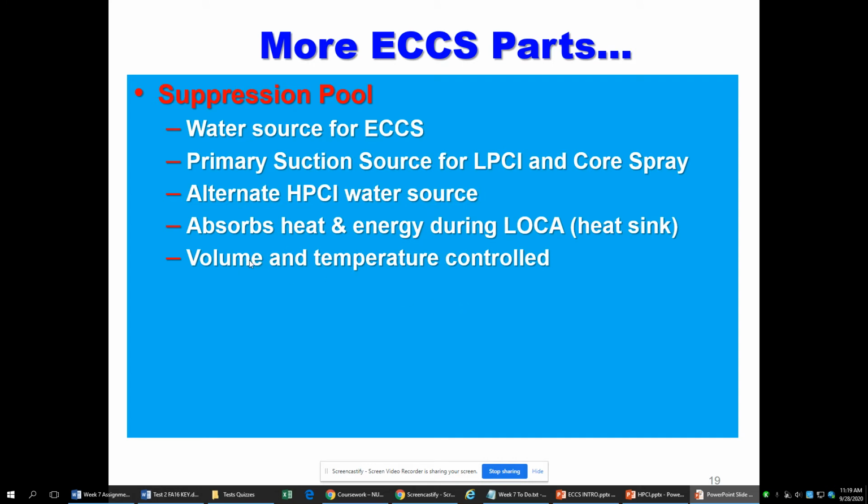And during normal times, we want to know how much water's in there because I might need to throw some steam in. So if it was full, my steam wouldn't go in. And we also want to make sure that it's temperature controlled, because if it's 200 degrees and I start shooting a bunch of steam in there, it's going to boil. And then I'm not going to have my source for LPCI and core spray if I boil the suppression pool.